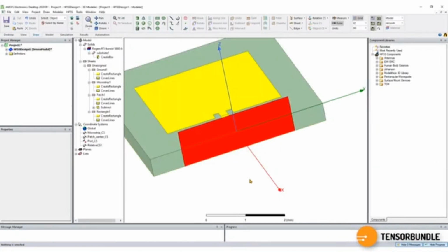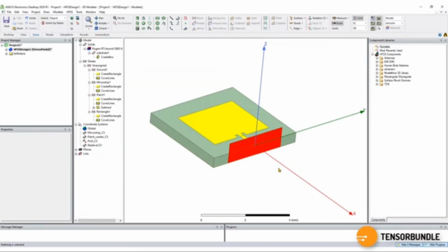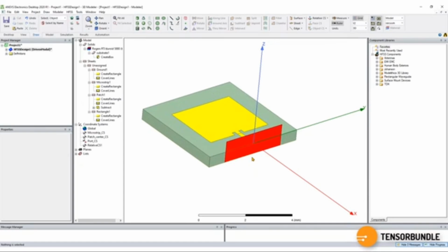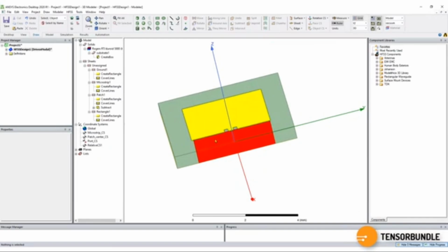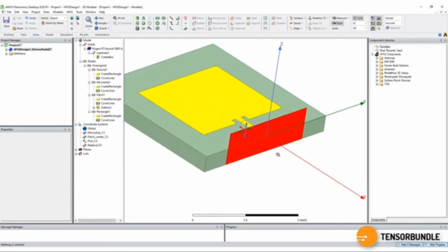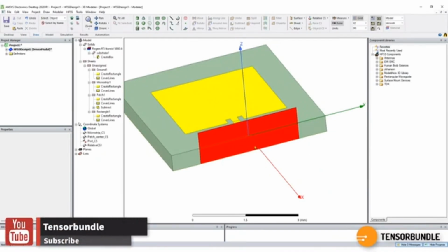All right. Since we're going to define a wave port, and in HFSS, if you want to keep the wave port inside the radiation boundary, you need to define the PEC cap on the back of the wave port. A PEC cap is just a metal boundary condition that is imposed on the backside of this wave port so that it can be placed inside a radiation boundary.